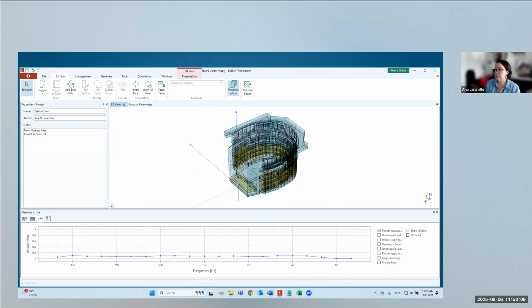When GLLs are imported from an EASE4 project file open in EASE5, the SPL is rolled off below 100 Hz and above 10K. This does not happen when placing a GLL in EASE5. Is there a way to adjust the frequency response back to flat broadband other than simply replacing the speaker with a new instance of the same GLL?